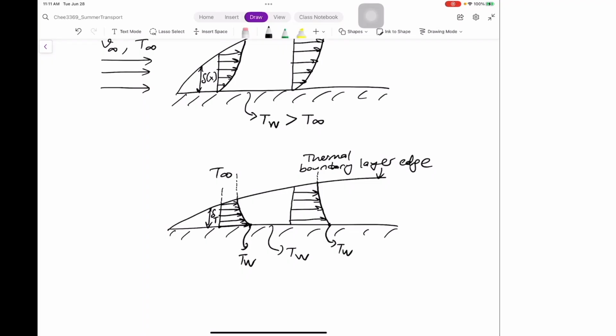The profile becoming flat means the following. There is no sense of any heat transfer around this, meaning that the plate is not felt by the fluid at this point, right? Similarly, here, the plate is not felt at a larger distance now, because most of the heat is being transferred to this part.